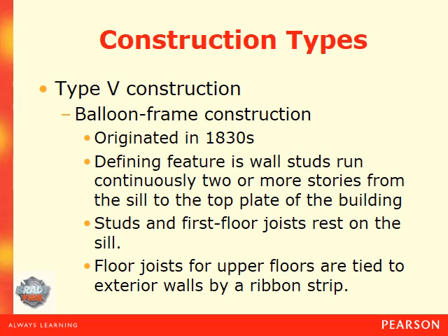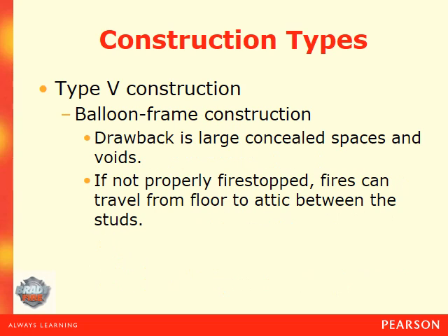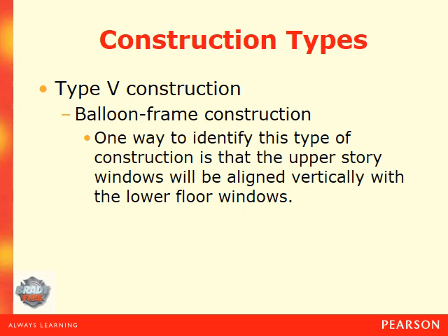So if you look at balloon frame construction, which originated in the 1830s, it had defining features in the wall studs that ran continuously up 2 or more stories from the bottom to the roof. And these wall studs had no fire breaks or stops in between the levels. So if you had a fire in the wall around the first floor or basement, it would run all the way up to the roof because they had these concealed spaces and voids, and would essentially burn the attic off and eventually destroy the structure.